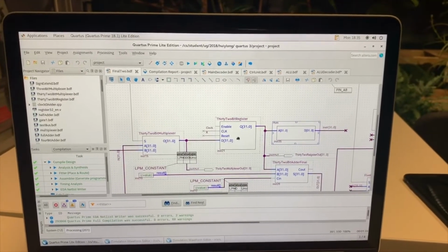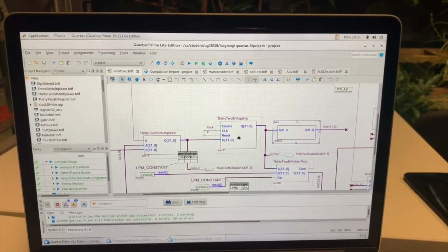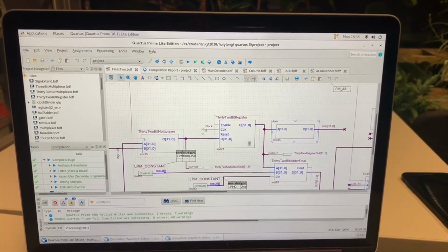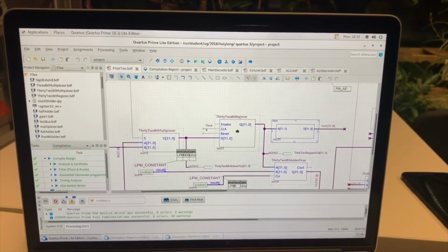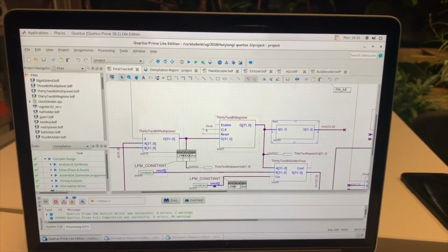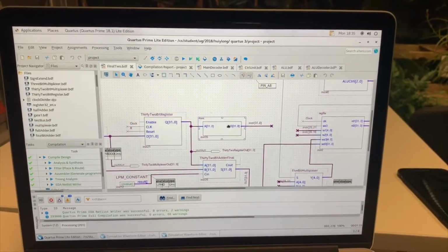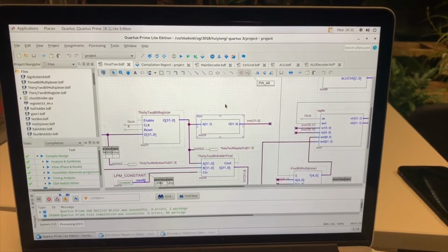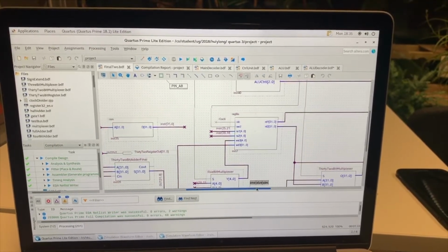Now, we will begin explaining different parts of our processor. We first start from the program counter. The program counter is a 32-bit resettable enable register made from our resettable enable D flip-flops. When the register is reset, the program counter sends an output to the ROM, also known as the read-only memory. The program counter will only deliver bits on the rising clock edge.